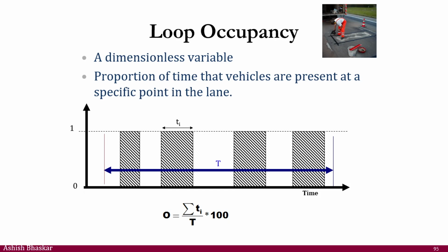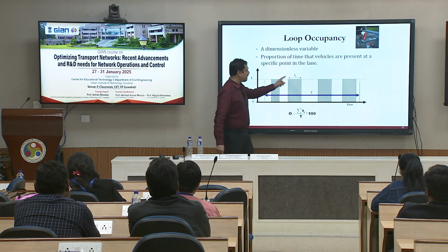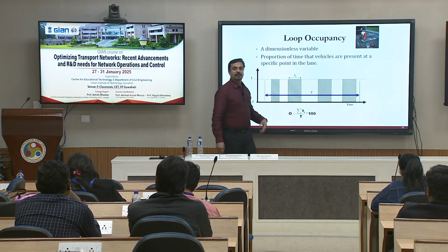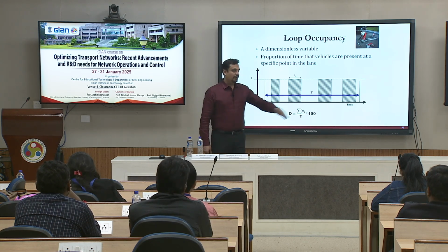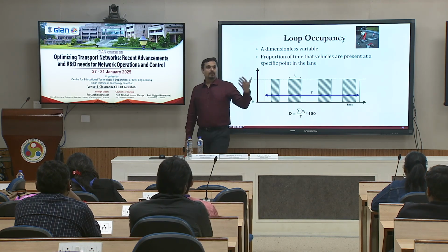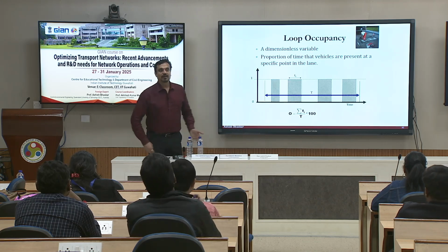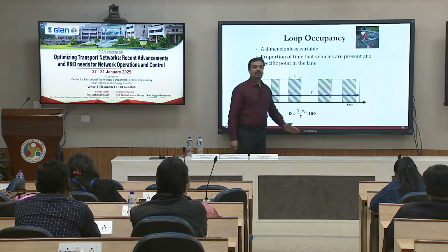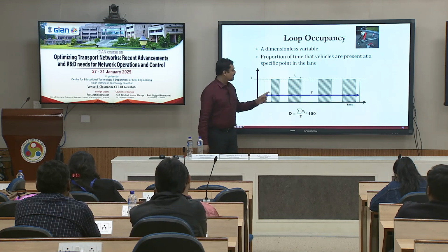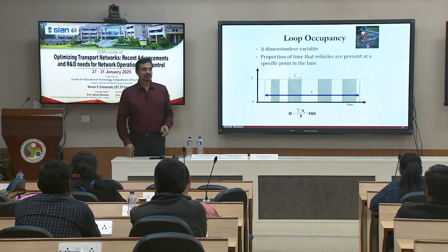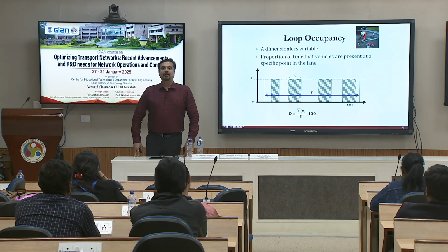In fact, we have discussed occupancy. If I look at my green time, you have pulses. Obviously, the percentage of the time my green was occupied is your green occupancy. So, if the traffic is flowing, this occupancy will be a high value, maybe 70, 80, 90. But if I say this time is my red time, do you expect this kind of pulses during the red time? Stop line loop detector, please. No? Why?